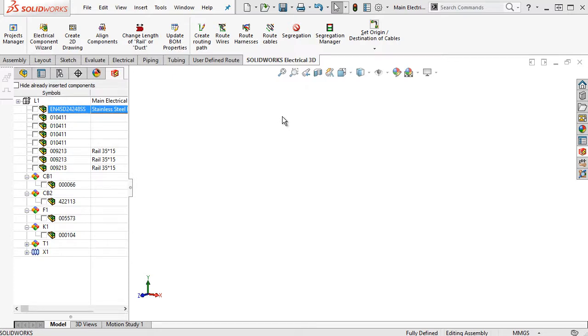Now that we have created and opened our new project assembly and added all the necessary components, we can start populating the assembly with those components. A logical starting point could be to first insert mechanical components such as your electrical enclosure, your ducts and rails, and then move on to inserting the electrical components such as your fuses, circuit breakers, and terminals.